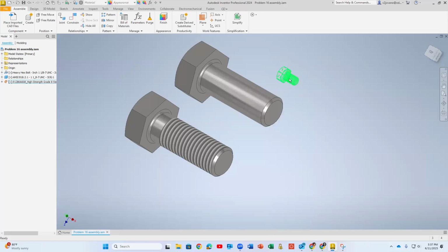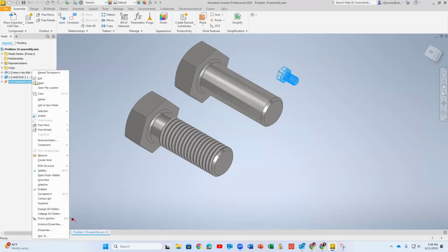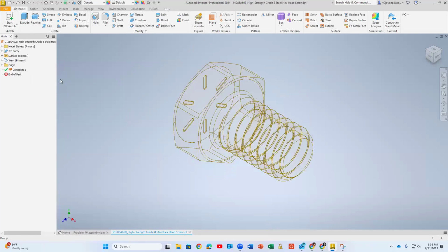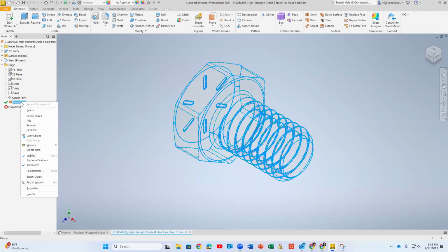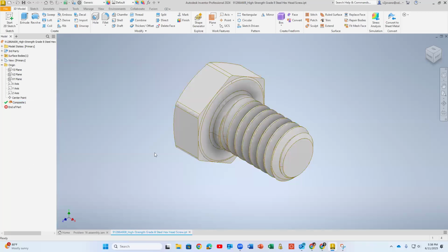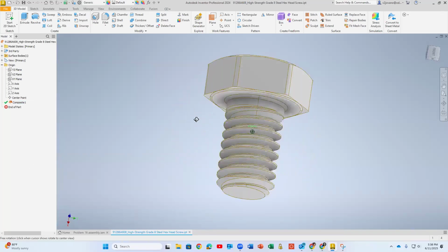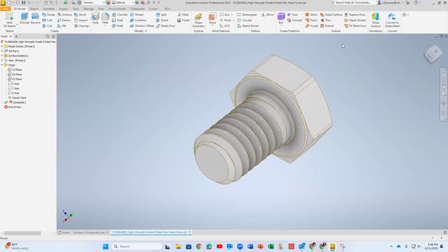I'm not seeing translucent as the book says in the version of Inventor that I'm using, but probably there's another option for this. Maybe I need to go into the part. So I'm right now in the part, so let me see if I will have it when I'm there. So it's showing me composite part, translucent. So you have to open a part, and then you will have an option to switch it so it looks like a solid. So you have to not be in an assembly.